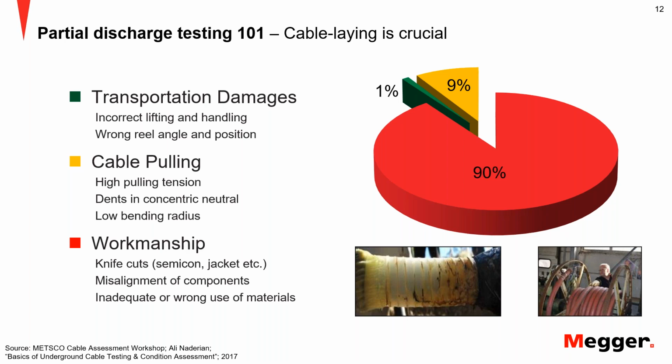So when you look at the distribution of the faults that you have and you try to assign them to a certain type of action, then cable pulling itself, like what you saw on this first picture, to get the cable there into the material and then covering with more sand, actually filling the trench, that phase is significant for causing problems, mainly due to sheath damage, and then simply the workmanship issues.